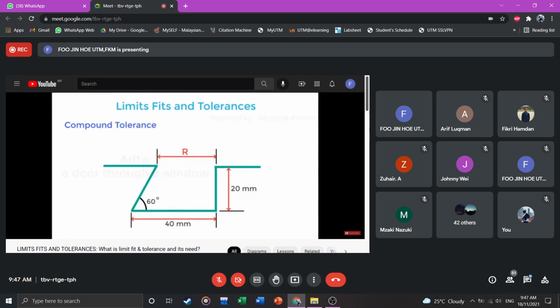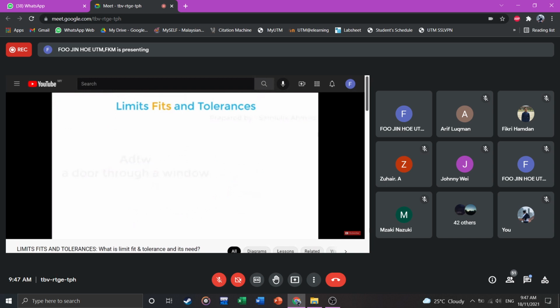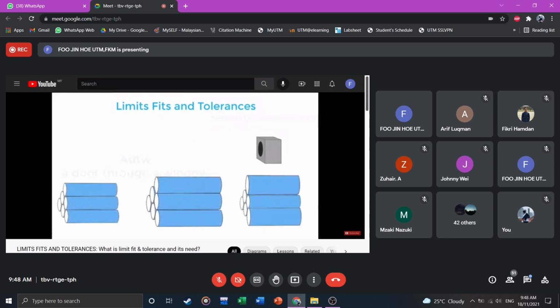Since we understood tolerance and what are its types, now we will see what fits means exactly. Fit means how well the manufactured components will fit together when they are assembled. There are three types of fits: clearance fit, interference fit, and transition fit. Let's take the example of shaft and hole to understand all three. Consider a hole has a fixed diameter of 25 mm, and there are many shafts which are divided into three groups. Consider first group of shafts.